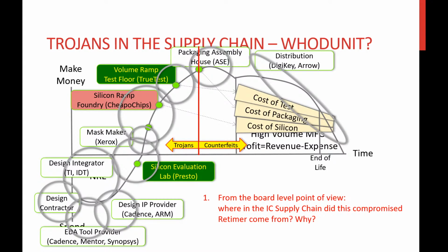Other facts that go with this line of thinking: the rogue fab foundry must have a related design house. The size of a retimer is fairly small, so in a normal wafer run, made up of sub-90 nanometer nodes, could result in 2,000 or more die per wafer.